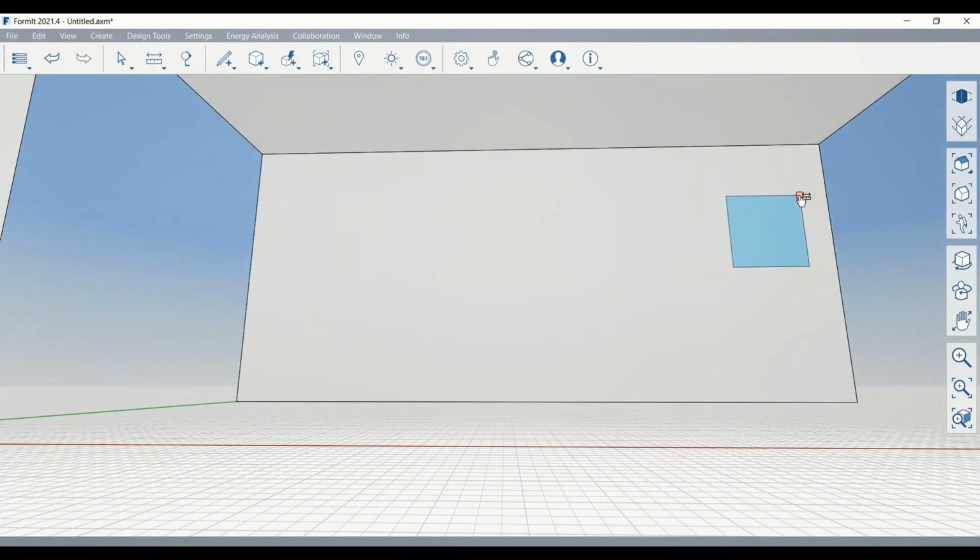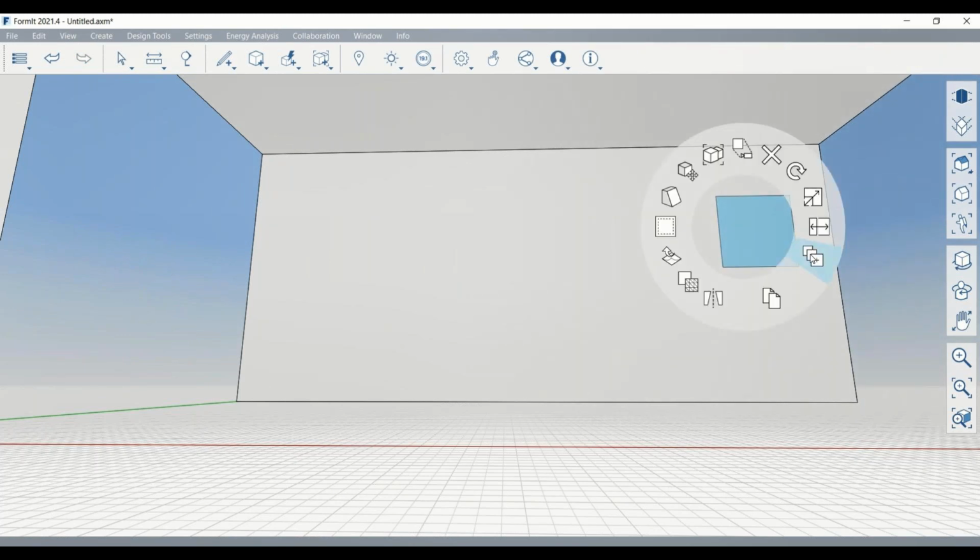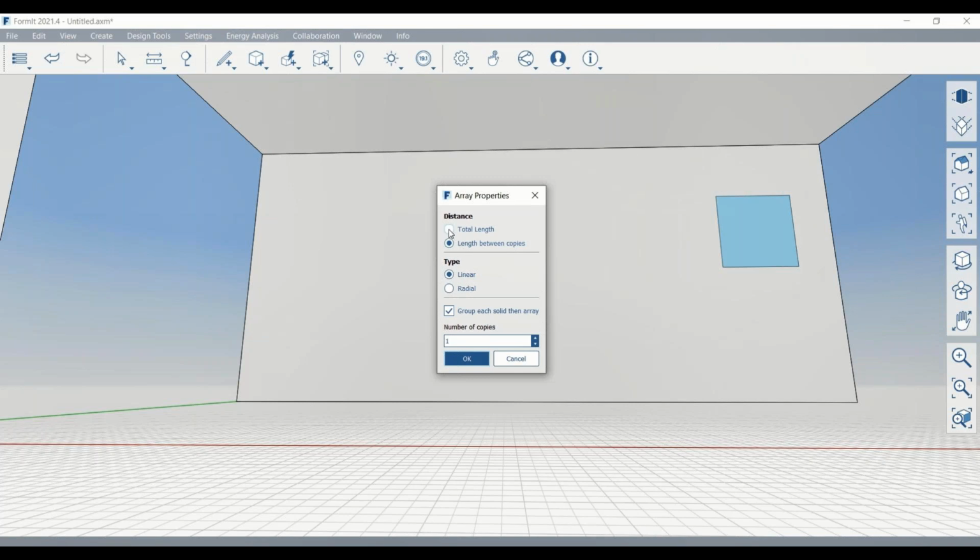Now, if we measure it, you can see it's giving me 361 at the moment. I'm going to change this to 500 and see what happens, right? Now, sometimes people make that mistake where it shifts the entire wall. That's not the correct way to actually do it, right? So how you would do it? Let's go back here and measure. I will click on that edge there, all right? So first we will click on there, select the second edge, and then it will go into that. So if you get it wrong the first time, just switch the order and then your shape will actually switch or shift.